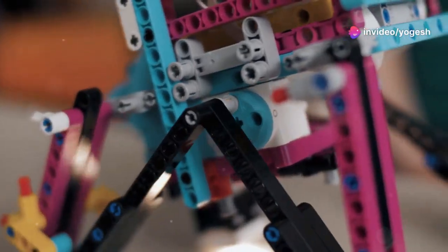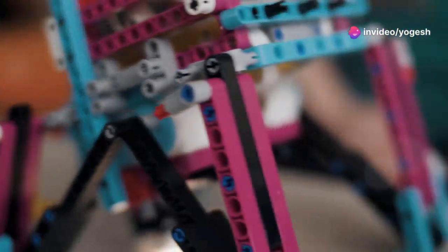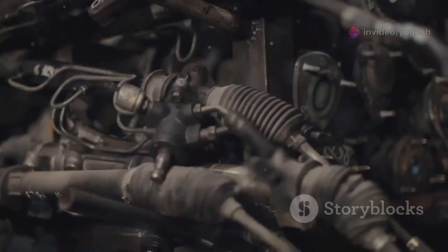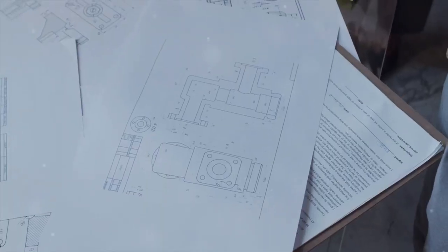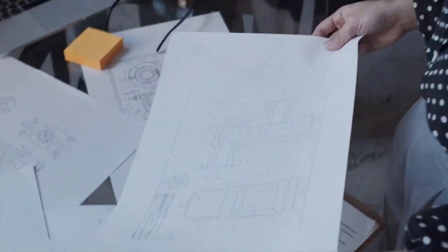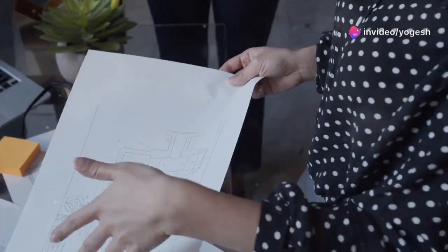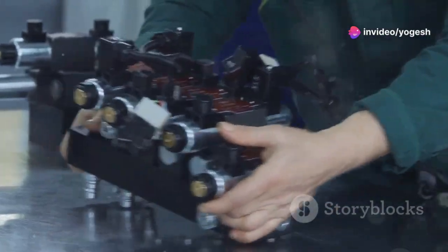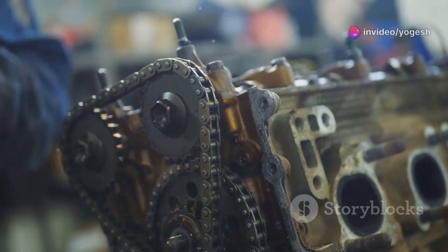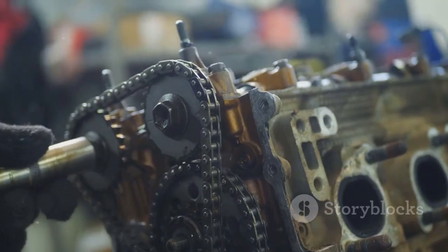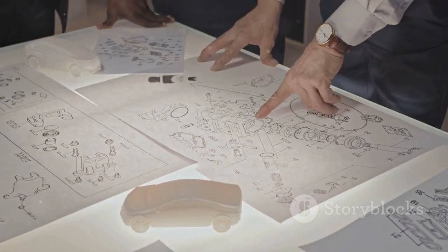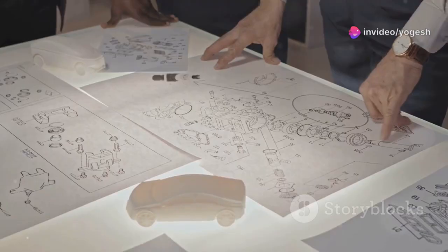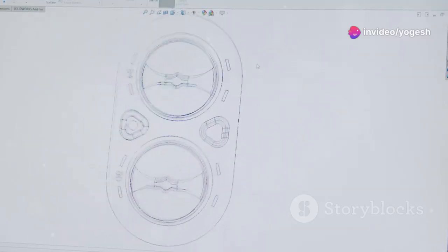The level of detail varies. Simple products may need only an exploded view, while complex assemblies require detailed subassembly instructions. Each subassembly has its own steps, all integrated into a master plan. Deviating from the prescribed sequence can cause parts not to fit, damage, or even catastrophic failure in safety-critical products. Treat the assembly sequence with the same importance as any dimension or tolerance. It's a core part of the product specification.